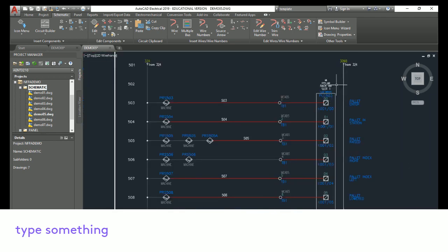It may show that I have a PLC rack or a slot for an I/O module in a PLC, but it's not going to tell me precisely where that slot is or where it's located in the control cabinet. So again, two sets of drawings that differ greatly in what they do. Schematics are going to show your wires and all your components and how they're wired together. And the panel is going to show the physical location of the hardware components as they're mounted. So you need both sets of those prints if you're going to build this machine.